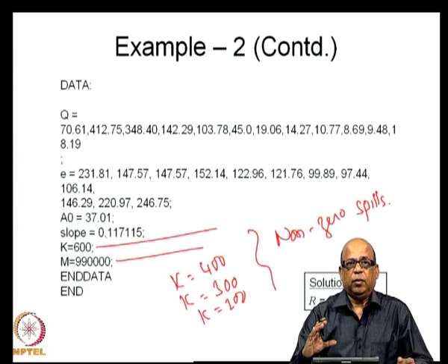So, that completes the topic on deciding on the reservoir capacity, where we are looking for the minimum required capacity for meeting a certain demand pattern with the inflow sequences pre-specified, for a given rate of evaporation losses that are taking place. So, that was the problem that we dealt with first, reservoir capacity determination. Then subsequently we talked about storage yield functions, where we are interested in obtaining the maximum constant release that can be made from a reservoir of known capacity.